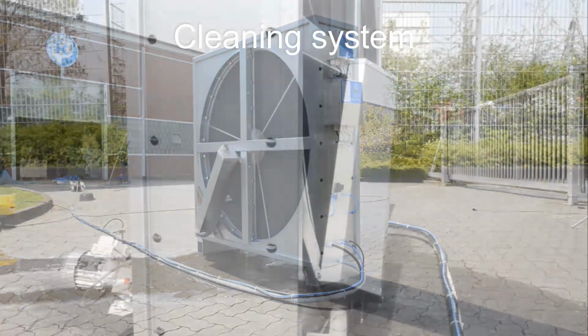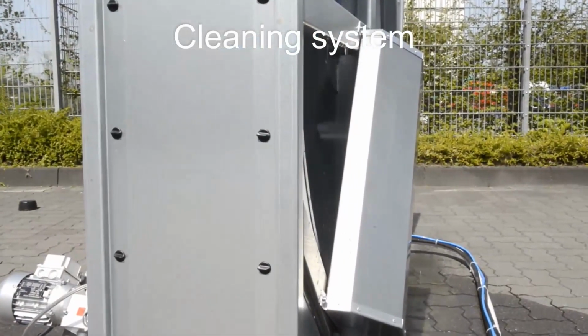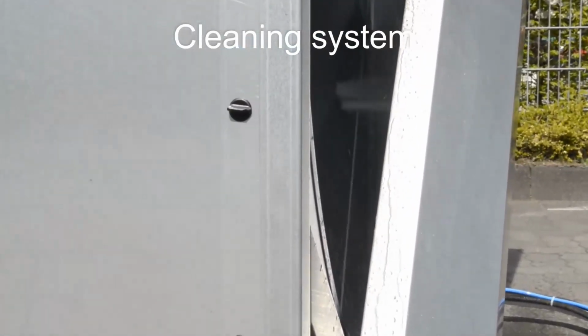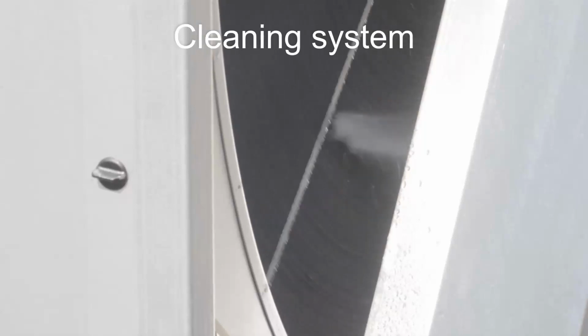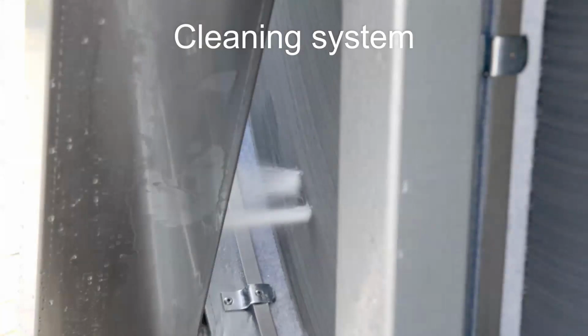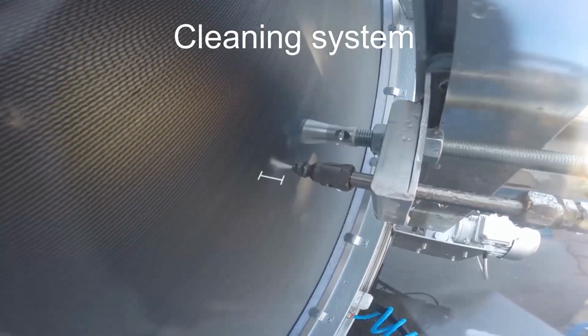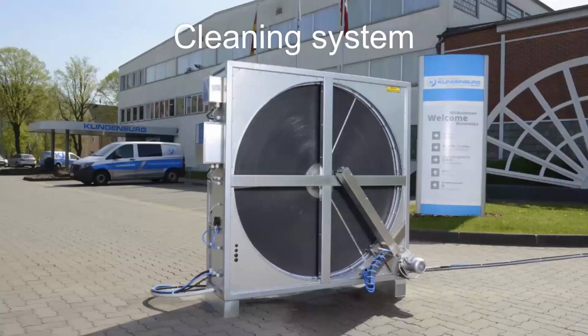And this is the other side of the wheel where you can see two jets of water being blown out into the evacuation tray. The reason why you see two water jets is very simple. There is one water jet that is blowing into the matrix with 140 bar of pressure. That's the first jet that you see at the exit. But in order to evacuate all of the water, there's a second nozzle, and that nozzle is compressed air. And this compressed air pushes out the rest of the remaining water. So you have a second water jet at the outlet, but you have only one at the inlet.